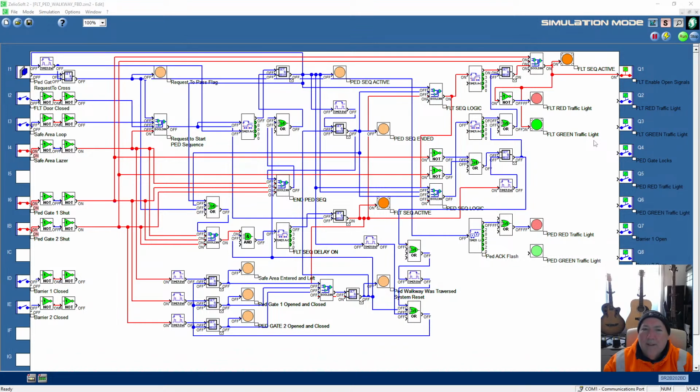Right, so we are in a state where, let's see what happens if we've got a pedestrian gate monitored maglock, and another one, to in and out. If the maglock isn't quite locked properly, or somebody kicks it or barges through, or it's faulty or something like that, these will click off, and there'll be a flag that gets remembered.